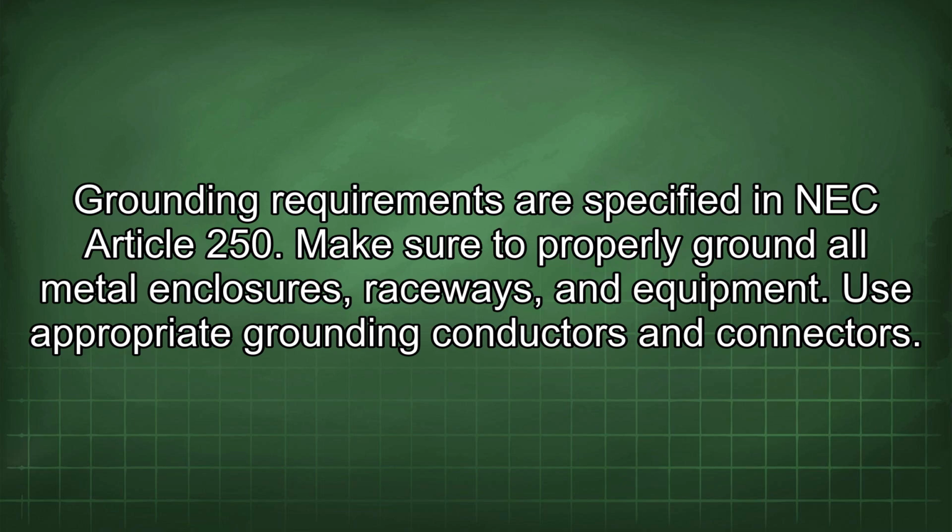Grounding requirements are specified in NEC Article 250. Make sure to properly ground all metal enclosures, raceways, and equipment. Use appropriate grounding conductors and connectors.